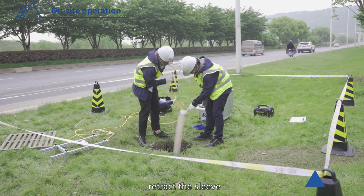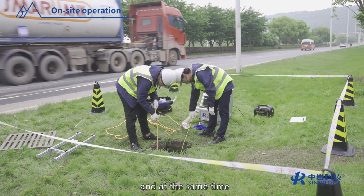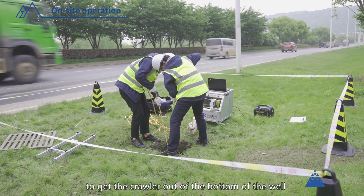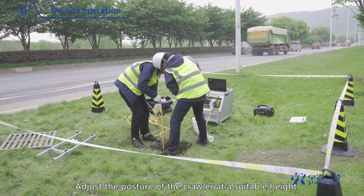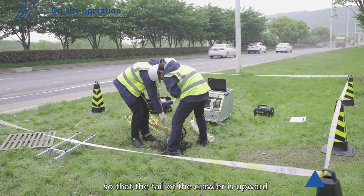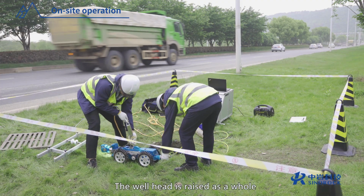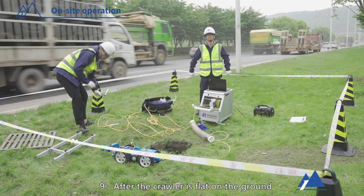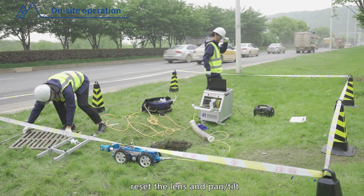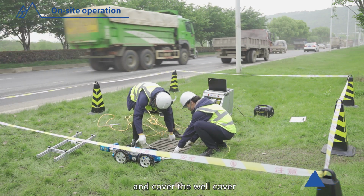Remove the wellhead frame, retract the sleeve, lower the hook to hook the crawler hook, and at the same time, lift the lanyard and cable to get the crawler out of the bottom of the well. Adjust the posture of the crawler at a suitable height, so that the tail of the crawler is upward and the lens is downward. The wellhead is raised as a whole. 9. After the crawler is flat on the ground, reset the lens and pan tilt. Turn off the lights, cut off the power, and cover the well cover.